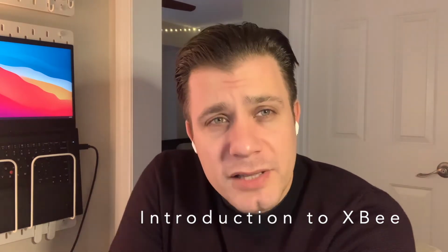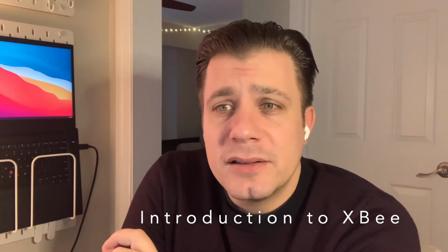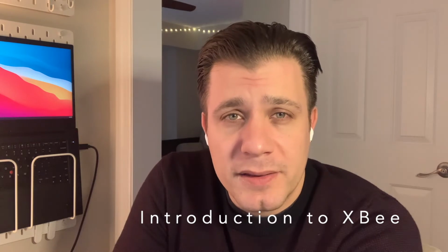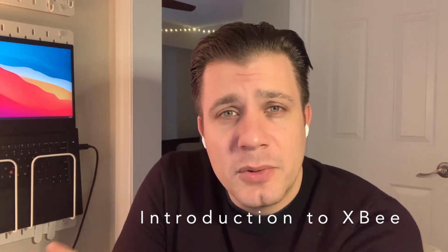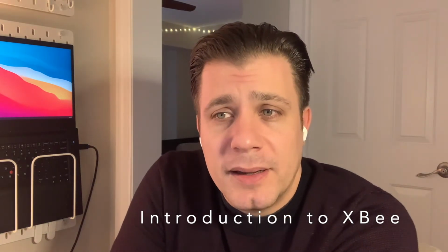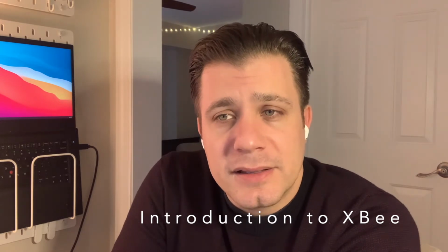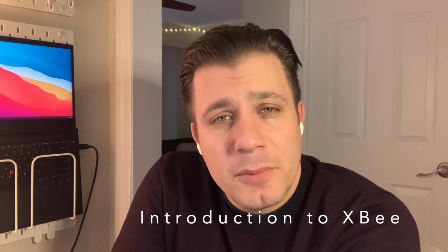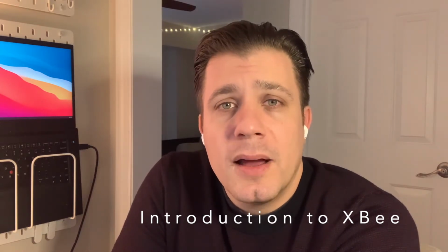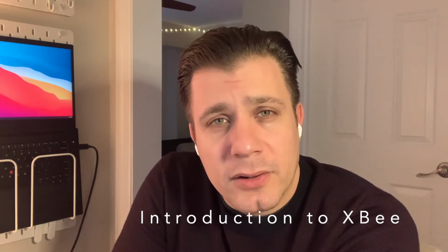Now, the newest type of radio, or the newest series, the XBee Series 3, facilitates multiple communication paths. It's actually backwards compatible with both the Series 1 and the Series 2. And so it allows you to communicate via ZigBee, and it also provides some Bluetooth capability in there. We'll talk about the Series 3 in a second and how that plays into this lesson. But the XBee radios employing ZigBee communication protocol predominantly transmit, at least for US versions, using a 2.4 gigahertz carrier frequency.